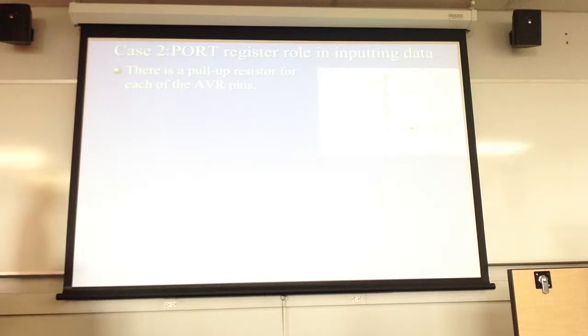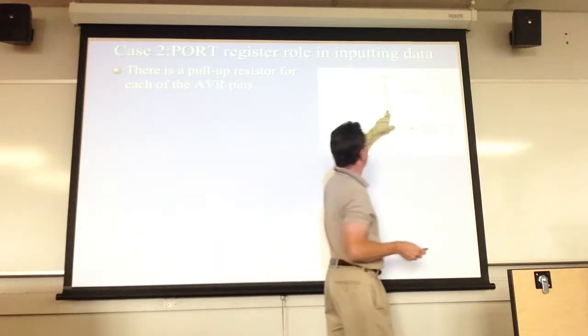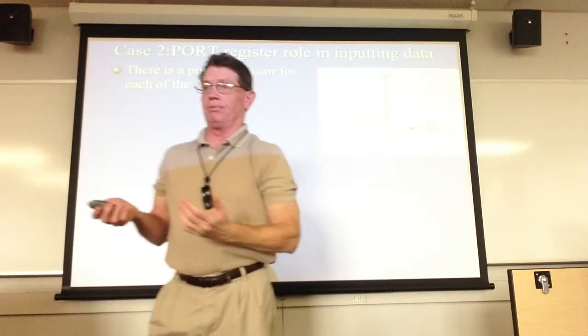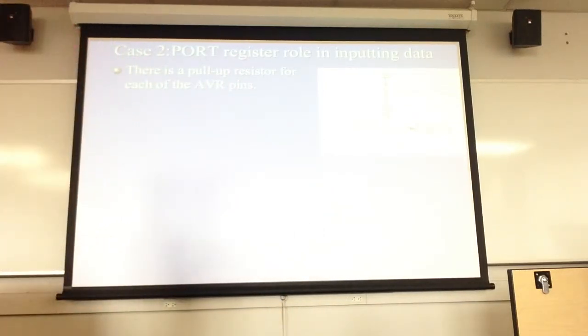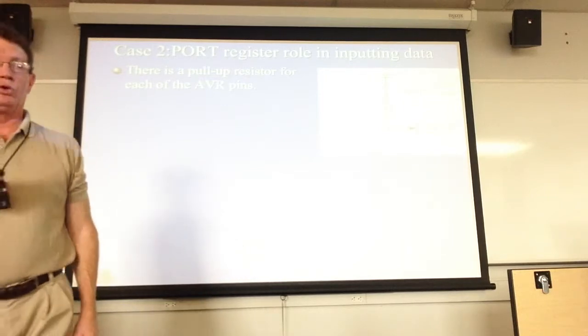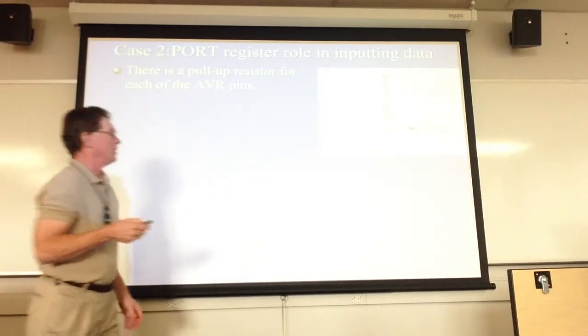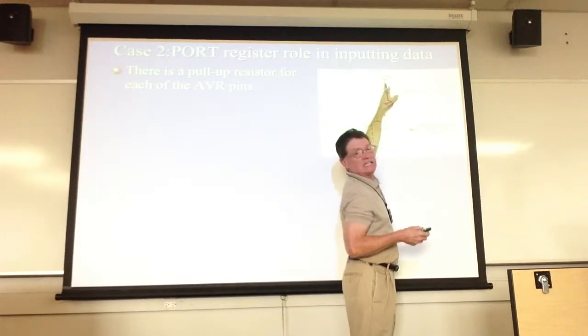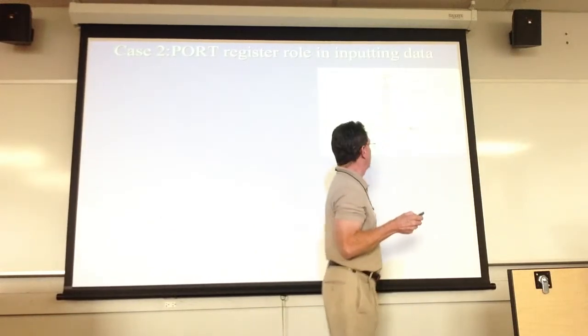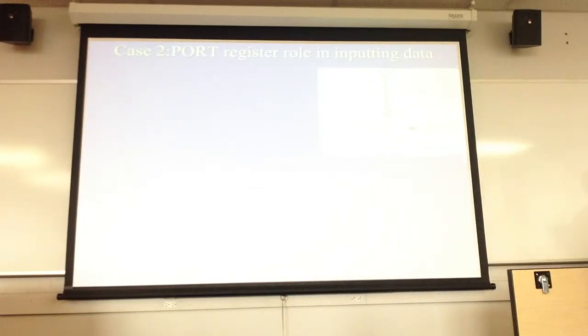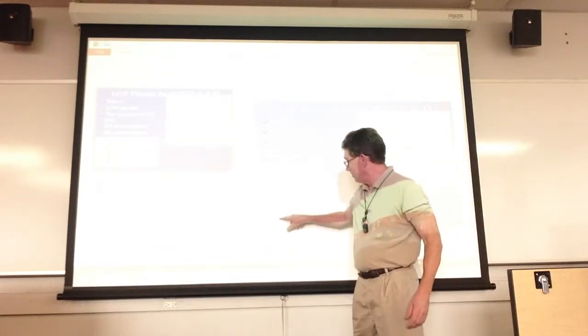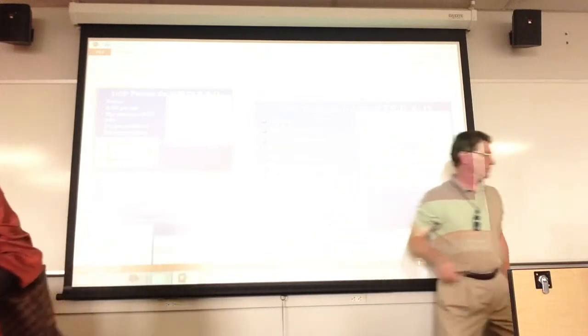There's what we call a pull-up resistor sitting up in here, all right? Now, this is something that we picked up when we started using this last year, that you have to set these bits if you want those pull-up resistors to be active. What effectively you have is VCC sitting next to this, that VCC is this VCC right here, and VCC and ground there, okay?